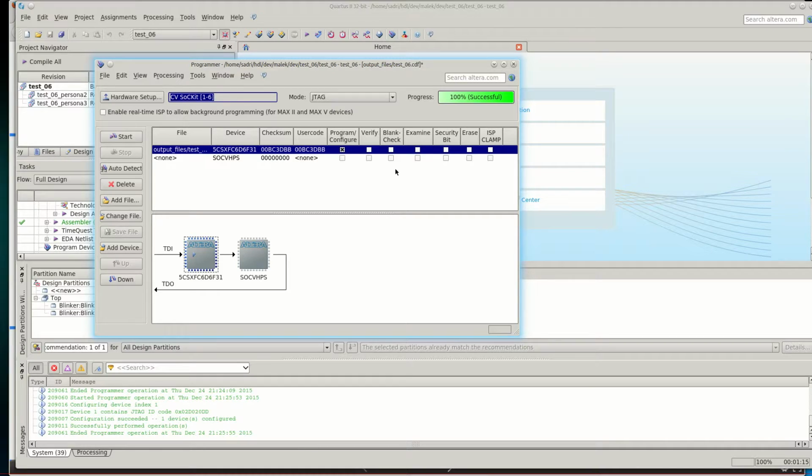And now I want to load in fact my first partial bitstream. So right now what we see is that LED 2 and LED 3 are blinking with a frequency defined in persona 2. So what I want to do is I want LED 2 to blink at the same frequency as LED 1. In order to do that, I should load one of my partial reconfiguration bitstreams.